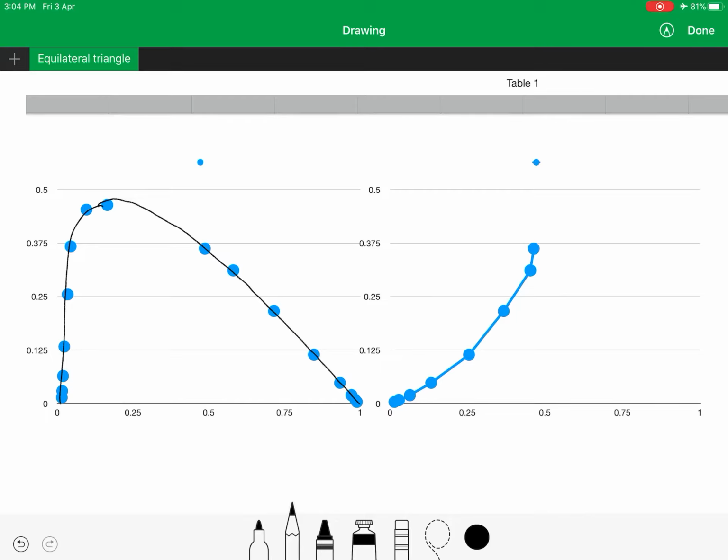This is the binodal curve, and in the previous lecture we discussed that with the binodal curve we must have the distribution curve, the distribution of only the solute in the raffinate as well as the extract phase.